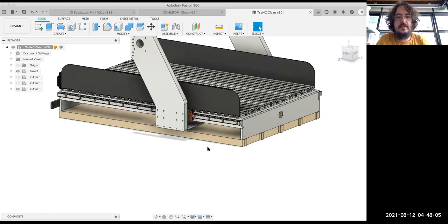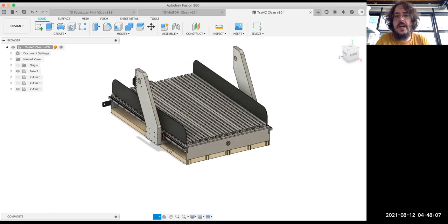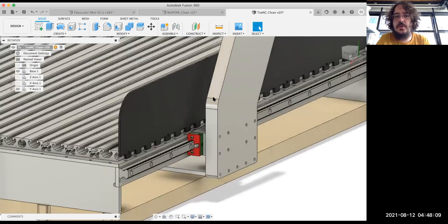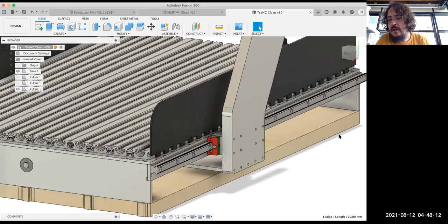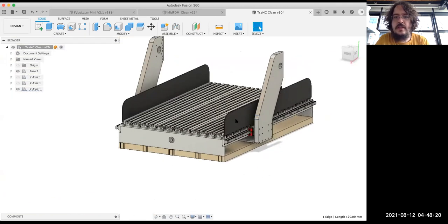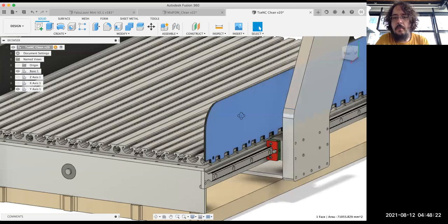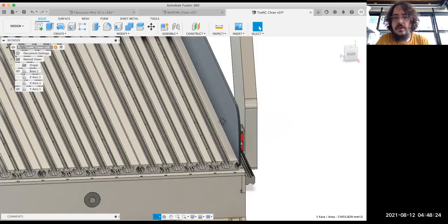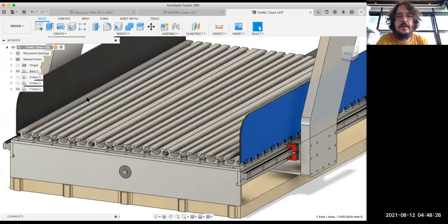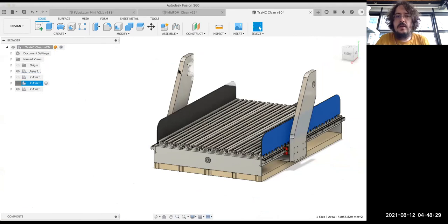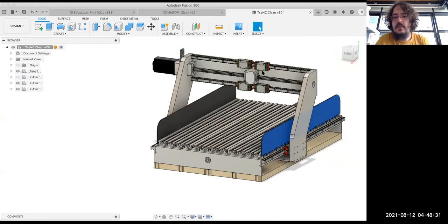So the y-axis is, again, this simple linear system. We have milled these gigantic shoulders out of 20 millimeter aluminum profile. So the whole machine is manufactured in my own Fab Lab with my own machines. This is laser cut POM to avoid that the dust will go into the linear guide over here. And then the whole system is still bolted to the frame.